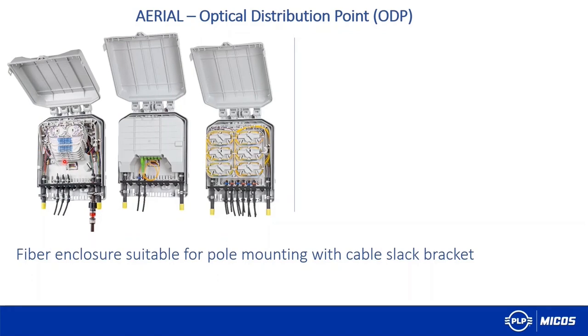But you can do it in three different ways. The first one I had in mind is only splicing. It means you come with the cable, make a loop or mid-span, and continue to the next pole, and you just make drops here, maybe 12 drops, and you connect 12 houses. And you do only splicing. It means one installation group does everything. This installation group is very professional, and they know how to splice and do everything.